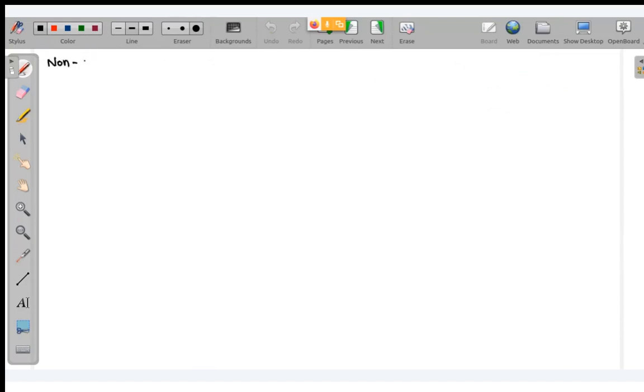So look over here now. In non-overlapping, remember that once the sequence is detected, you cannot take the bit of the previous sequence. You cannot take it. So once again, you are going to start from idle. Okay.